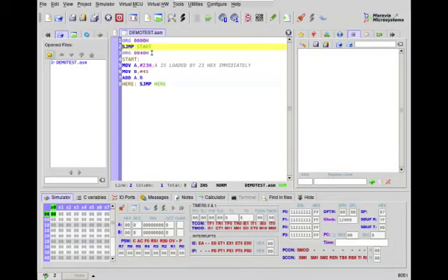Because in between 0000 and 0040 there are the vector addresses of the interrupts. So we are skipping those vector addresses of the interrupts and directly jumping to 0040. This is a general practice of writing a microcontroller assembly language program.